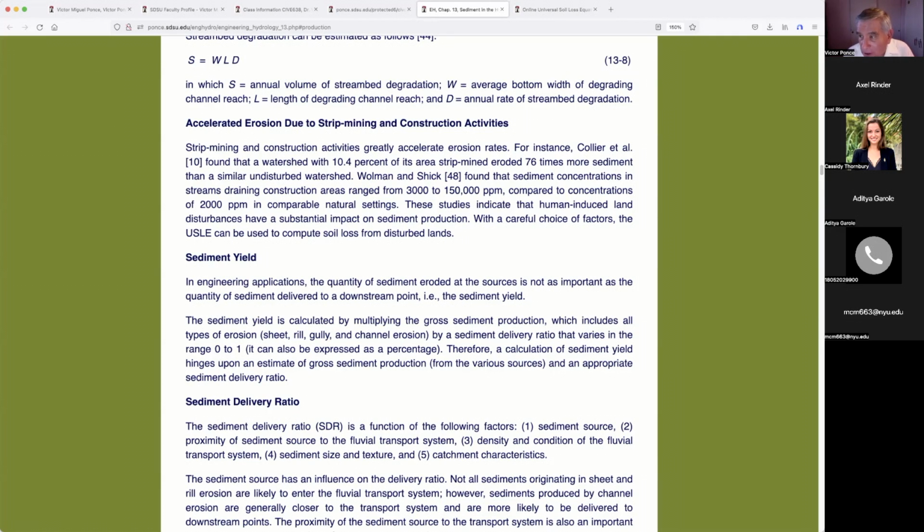What had happened was that the two dams did their job of holding on to all the sediment. Not all, but a large portion of it. Let's say it could be calculated. But it produced hungry water, quote unquote, hungry water. The sediment had been taken out of the water and deposited in the two reservoirs, which are specific sediment retention reservoirs, and then it came downstream of the two dams hungry, and it proceeded to erode to datum, about 5 feet. That's the picture that I've shown you earlier.